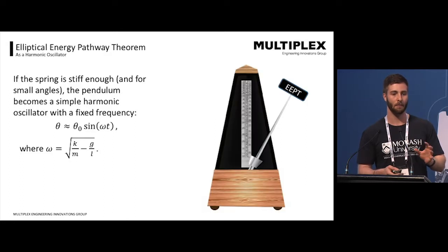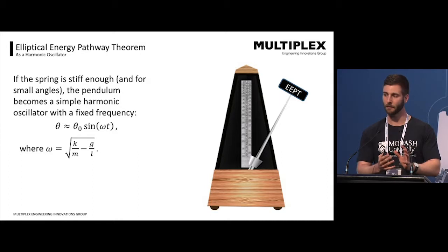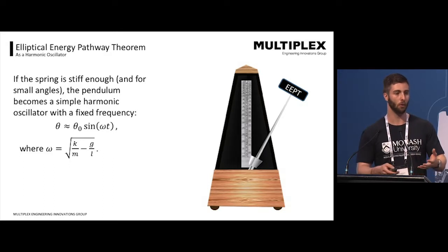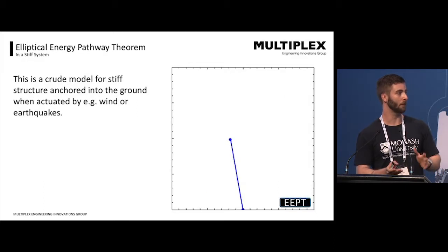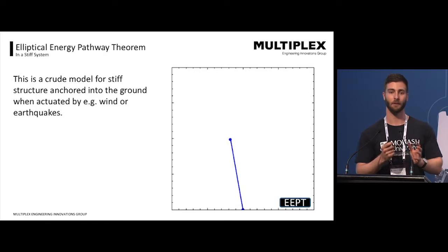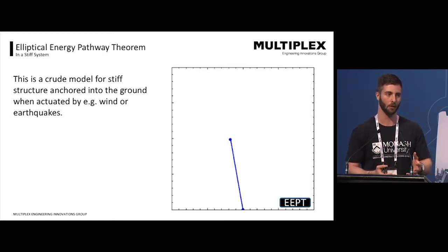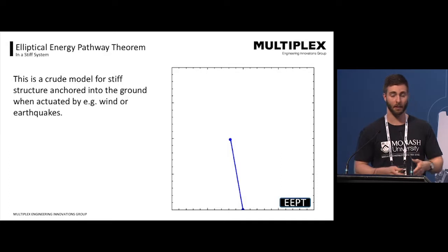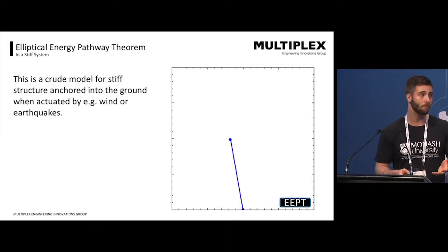It's a little bit like a metronome in that you get a certain frequency out of it. You can increase the stiffness of the system and change how it's going to act, what the frequency will be. Effectively, this is how buildings are thought of. You increase your stiffness or add, say, a tuned mass damper or other measures to a building to try and control how it moves. We look at how it moves, basically just back and forward as one rigid system. So it's a very simple way of thinking of a building, a very simple way of designing, but it is often the way that it's done.